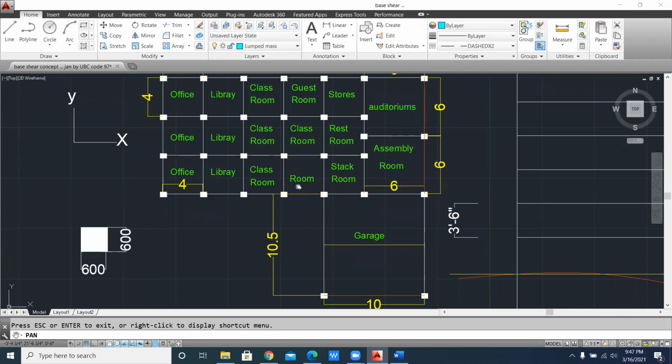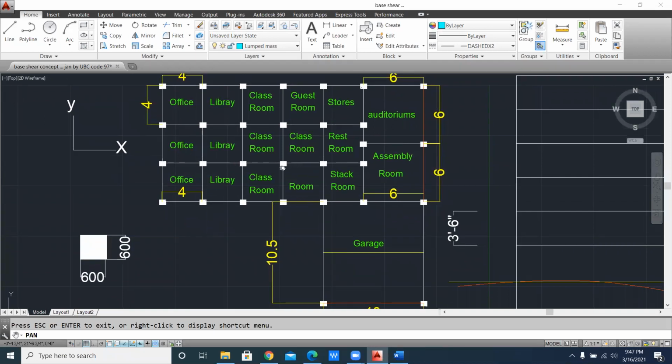What is live load? Live load is normally movable. That is called live load. Some people take other factors, like the seismic factor, as live load, but that is not live load. Always remember that your environmental load is not taken as a live load, because it is normally your environmental load. Live load is when any human goes up and down, or you place something on top, and it is removable. That is called live load.